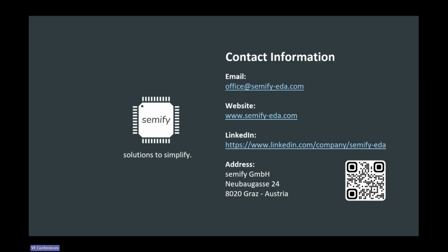Maybe just trying to understand the model. Does it do pulse swallowing? So you can swallow a pulse. Also a very good question. With naive modeling, there's another way you could do this where on every data input, for example, you randomize the first bit of the synchronizer. But this does exactly what you say, where it filters out certain data, which is really bad because then you lead into these false positive bugs. This would never happen in hardware.